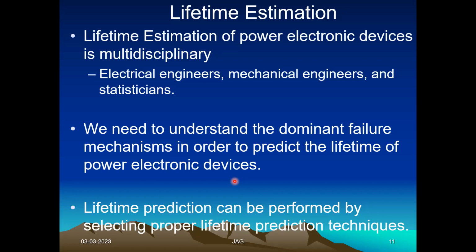Then the mechanical engineer. That person is the engineer behind removing the heat energy from the junction of the semiconductor. Am I right? Heat energy will be generated in the junction of the semiconductor, which will be dissipated to the surroundings using heat sinks. Natural cooling also is there. If the temperature is not that high, better you don't use any heat management. Automatically, the temperature will come down after some time, because the generated energy is getting dissipated to the surrounding air.